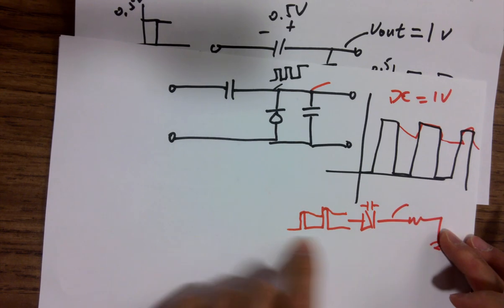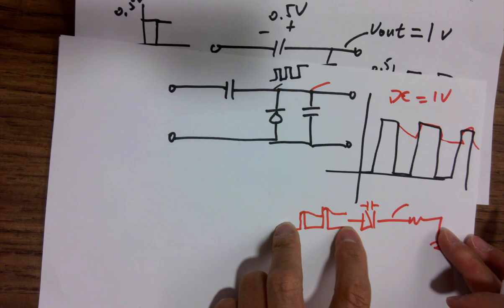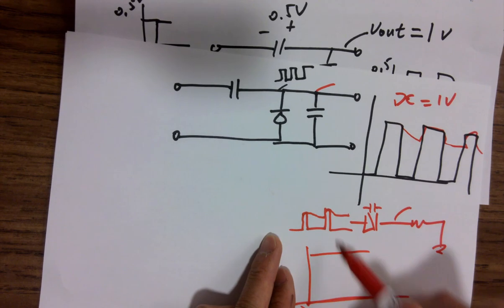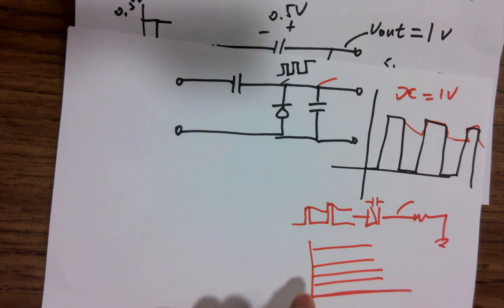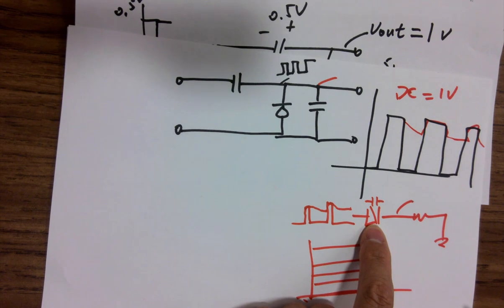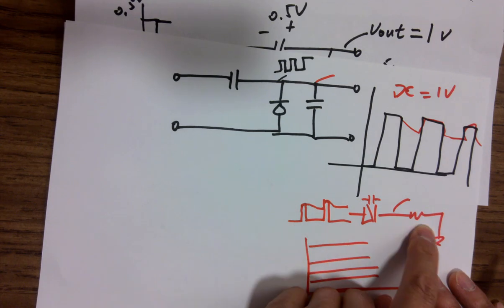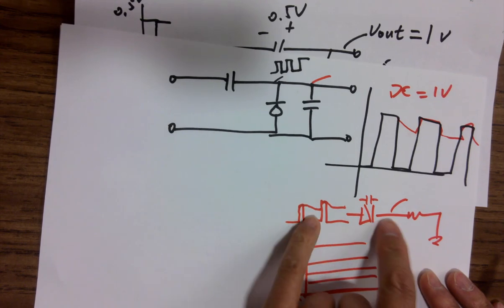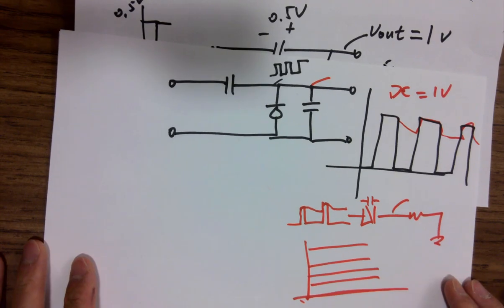Okay, that's one part. Another part is it's being blinked. So if you consider the output power compared to the DC power, like 5 volts, if you do a PWM, depending on the duty cycle, you can reduce the overall power being delivered to the LED by different DC levels. It's equivalent power being delivered to the LED, so you are seeing this being dimmed. But we don't really care about the DC of the junction capacitor and the low pass filter circuit. We just look at the power of the PWM. We don't look into the rectified voltage output. Okay.